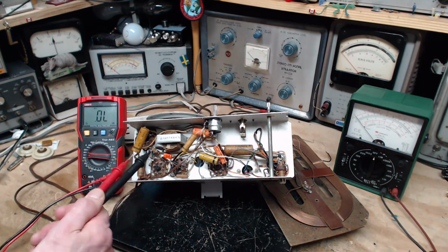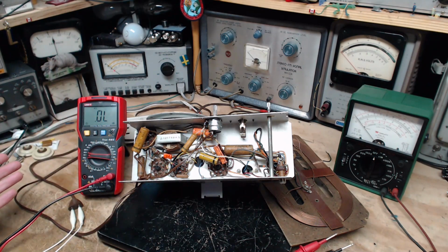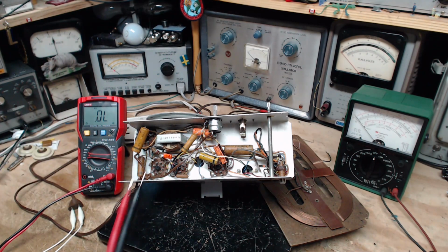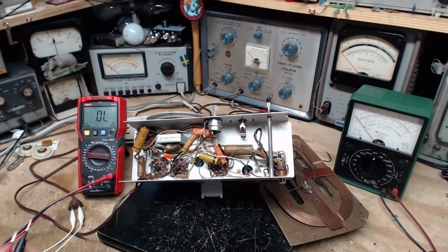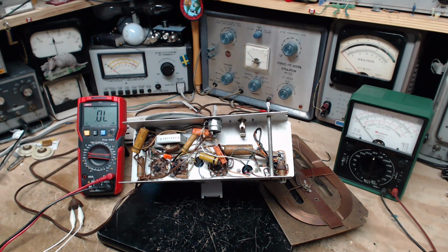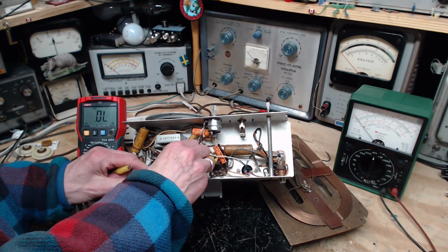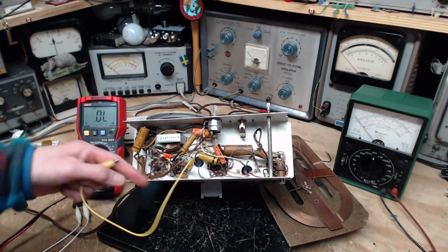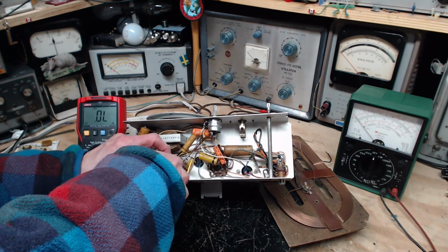So with that resistor there, that's the main control on the rate at which current is going to leak into this, into here, I would think. I would think if I nip that, we would then see only the capacitor. And for the sake of the experiment I'm doing, that's what I'm going to do. I'm going to nip that resistor, even though it appears to be just fine, to get it out of the circuit, and leave only the capacitor behind. I'll just solder it back later. There's lots of excess lead here. It'd be easy to do.